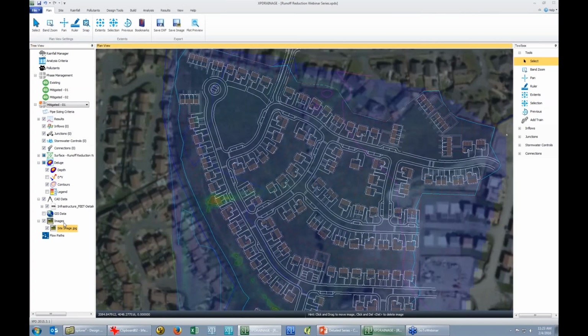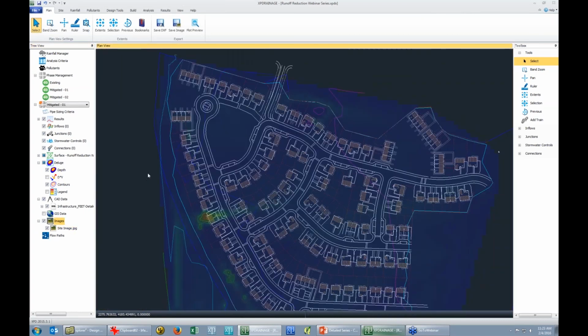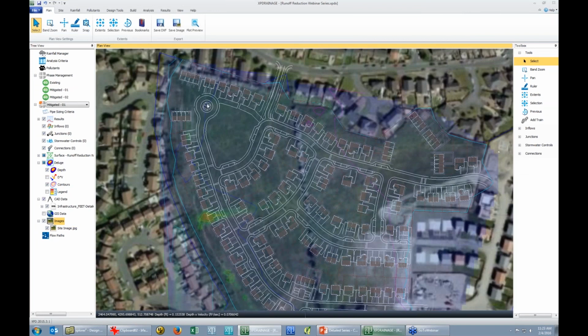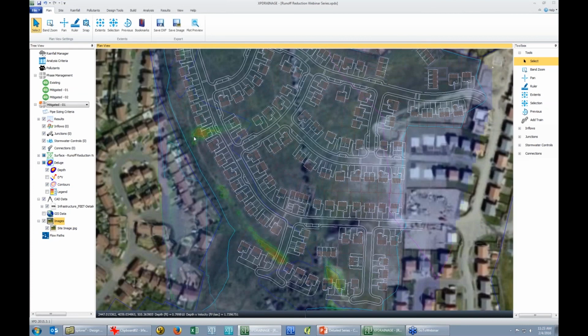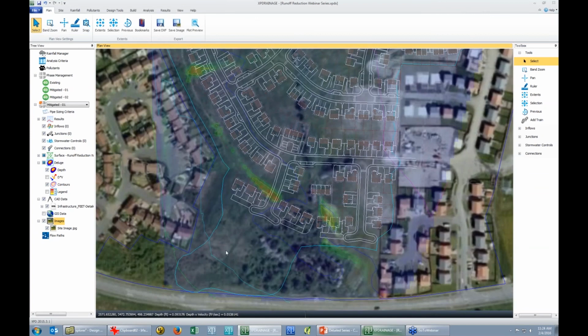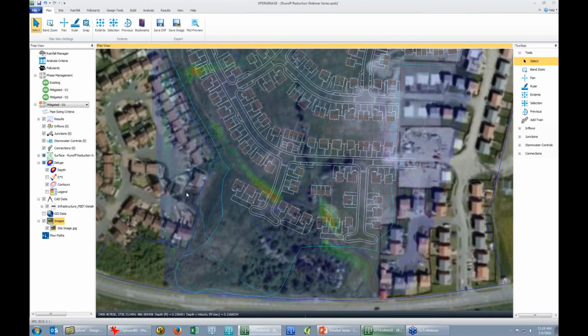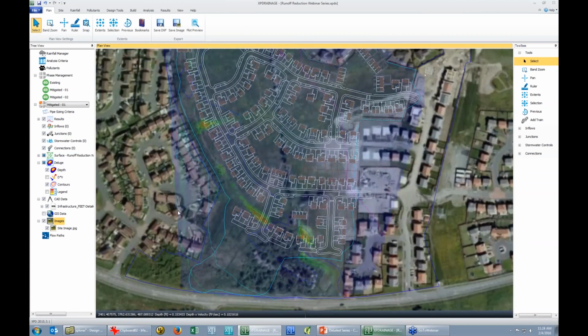you can really delineate perhaps your inflow areas. All right, you can delineate your site. You'll see here the majority of volume on our site runs to this southern section, southwest, and ultimately down here into this marshy area. Well, that's ultimately a good place for a pond, probably, kind of a catch-all high volume system. So this is how we plan out our site.